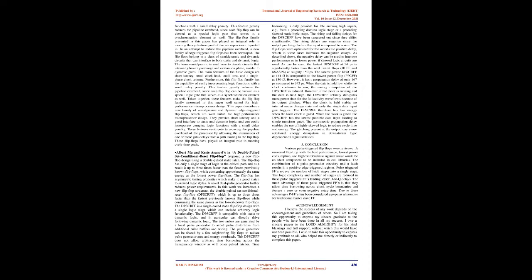Further, they developed a method for accurate measurement of flip-flop parameters from the test chip. They obtained very good measurement accuracy of 10 ps under difficult conditions characterized by high test frequency. This flip-flop was implemented on a test chip in 0.18 µm CMOS technology. The measurement results place it on top in terms of speed as compared to other flip-flops used in high-performance processors.